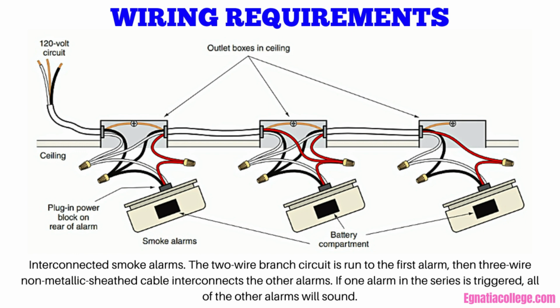Battery-operated units. These units require no wiring, they are simply mounted in the desired locations. Batteries last for about a year. Battery-operated units should be tested periodically, as recommended by the manufacturer. Always follow the installation requirements and recommendations of the unit manufacturer. Refer to the ULC standards for additional technical data relating to the installation of smoke and heat detectors.